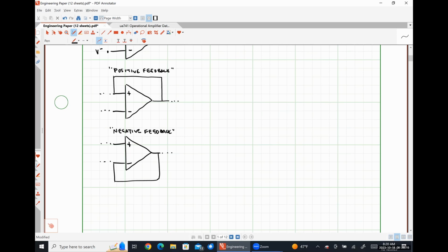So all of our circuits are going to have some feedback path from the inverting input terminal to our output terminal, usually in the form of a resistor, but sometimes it could be a capacitor or inductor, depending on what type of mathematical operation we're trying to get our operational amplifier to do for us, right? An operational amplifier is called that because it is a circuit that does mathematical operations on continuous time input signals, right?